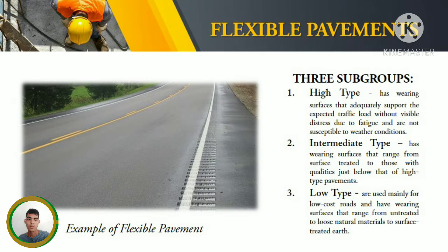Furthermore, the flexible pavement is divided into three subgroups. The first one is the high type pavement. It has wearing surfaces that adequately support the expected traffic load without visible distress due to fatigue and are not susceptible to weather conditions. Secondly, the intermediate type.